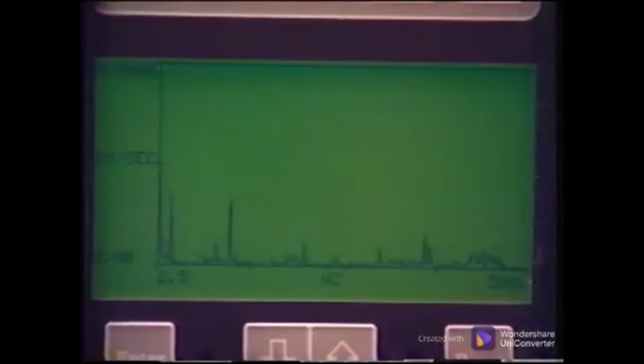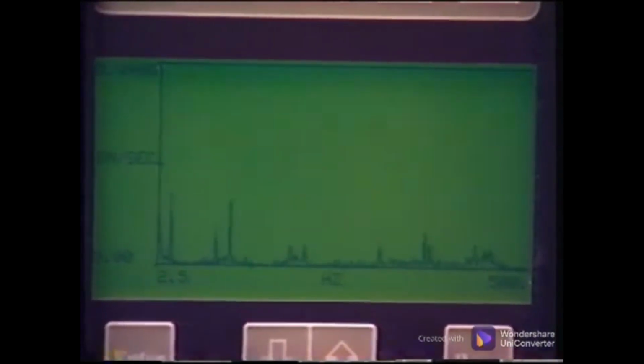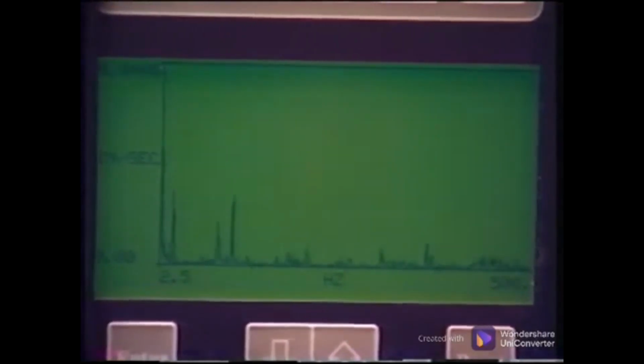Another benefit of the magnets over the stingers is they hold themselves on with the same force time after time to give you greater repeatability for your data month after month. Studies have shown that data varies substantially depending on the pressure used with a stinger. When data is collected by different personnel, the data varies even more, which makes trending data risky at best. For this reason, it is often difficult to get good repeatable data with handheld mountings.